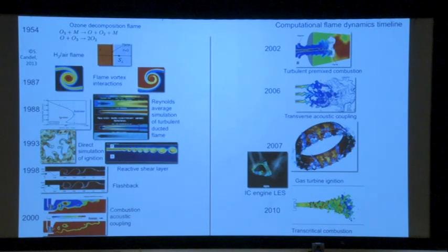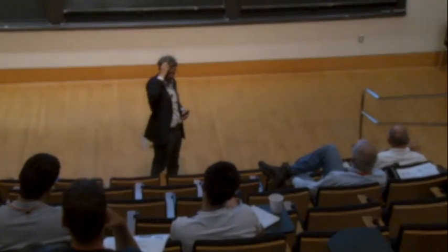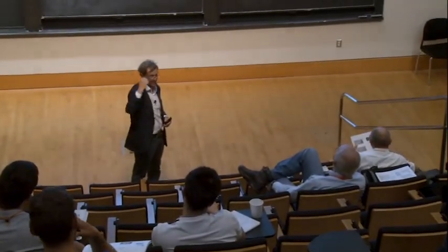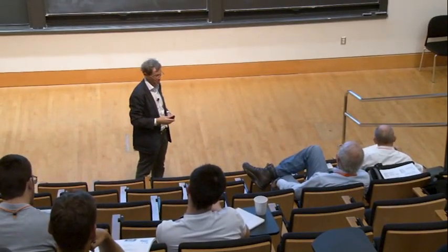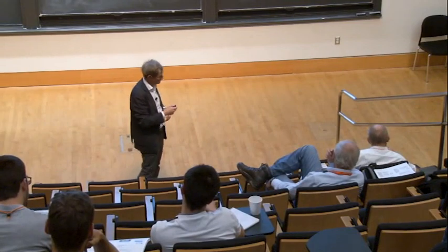There is also a lot of work on IC engine LES now. And we worked very much on combustion at very high pressure in transcritical situations, above the thermodynamic critical point. This is oxygen injected at very low temperature and high pressure, above the critical point of oxygen. And this is difficult because you have real gas effects, another complexity, and we are able now to calculate such flames.